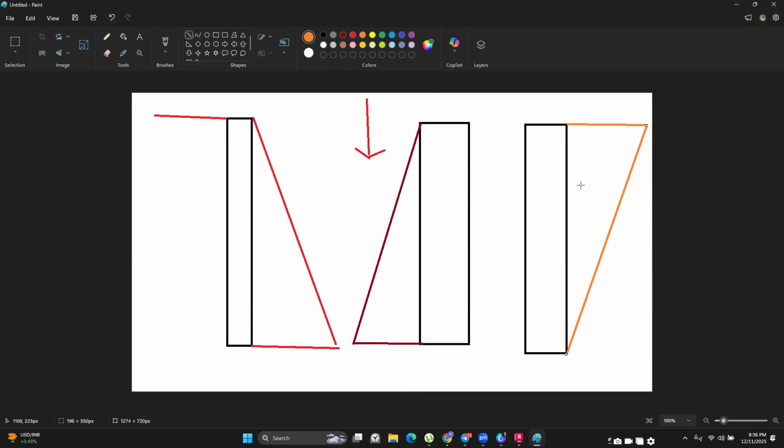This will also give you erroneous results because, if you remember correctly, the maximum pressure from this soil will be acting at a third. The effective area of this shape is usually at a third from this point here, or 2/3 from this point here. So in this particular scenario, you'd expect the pressure to be done at such a point here.